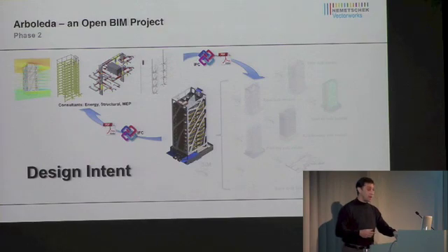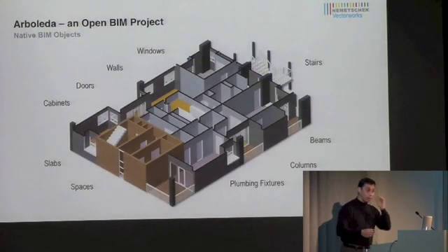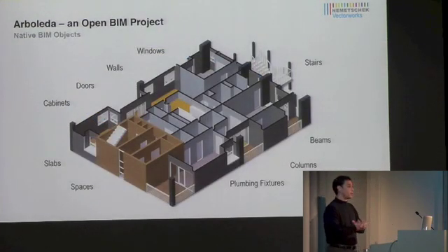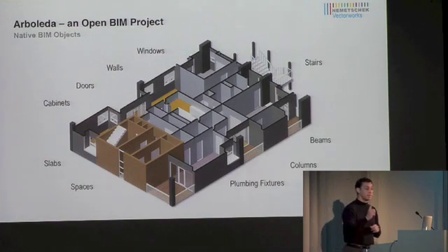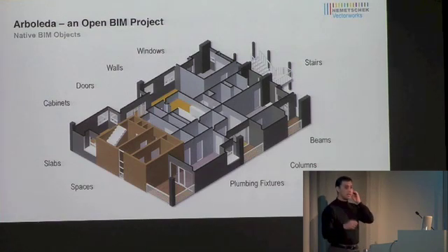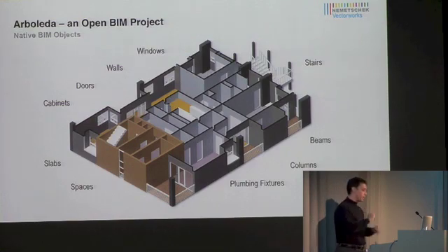But in order to send it out, well, first you have to remember, I use only objects from Vectorworks that have IFC information attached, ready to go. Slabs, spaces, stairs, beams, columns, only those objects, except for the skin of the building. I have to attach IFC information manually.